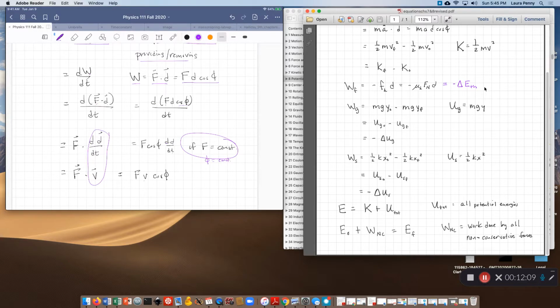Then we can write it either as the dot product of the force with the velocity. This is our instantaneous power. Or what we already know about dot products, which is the amount of the force, the amount of the velocity, and the cosine of the angle between them. So here this would be the angle, as always, between our two vectors that we're considering in the dot product.